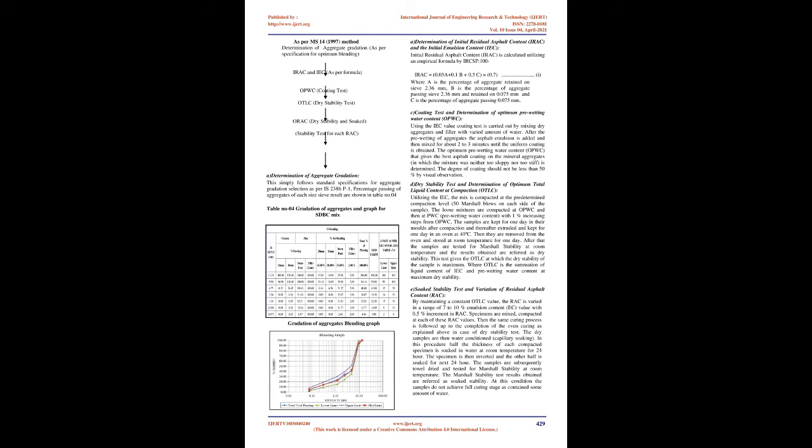In Table No. 03 are shown the parameters and testing results of SS1 grade bituminous emulsion. 3. Method of cold mix. A. The bituminous binders used in cold mixes are emulsified and hence in liquid form. So, it can be applied at relatively low temperatures compared to that of hot mix.